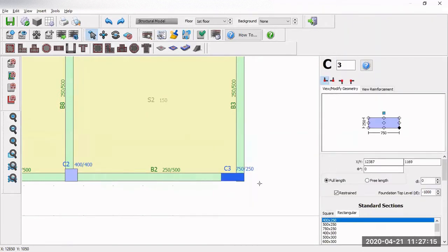All right. So maybe just now, as I mentioned just now, this value here are very close to 1, exceeding 1. So for safety reason, I want to concrete jacket to strengthening these columns. So what I'm going to do is I'm going to apply the jacketed rectangular section to this column. All right. So in this column here is C3. So we select this function, insert jacket rectangular column.